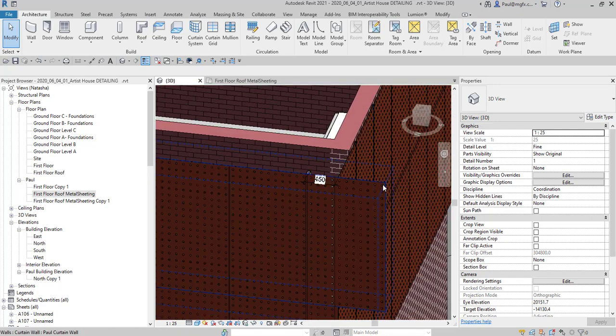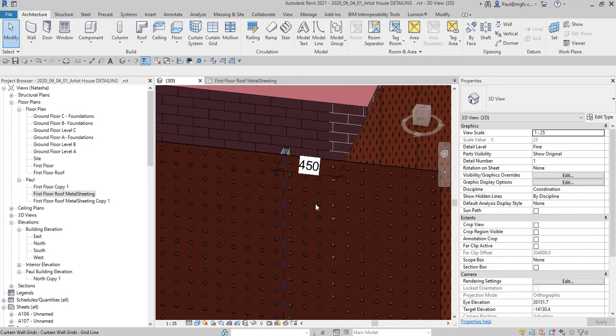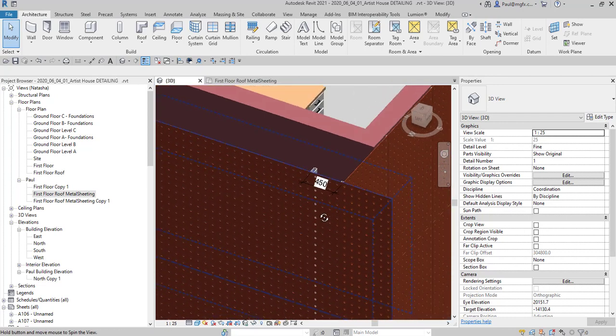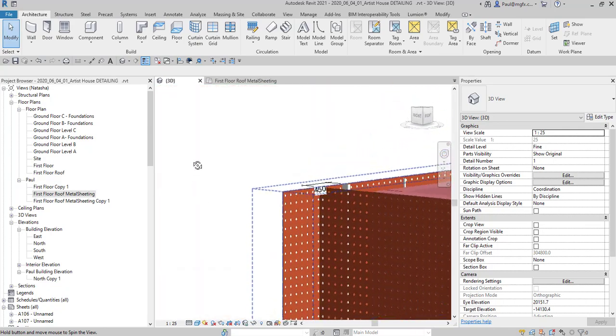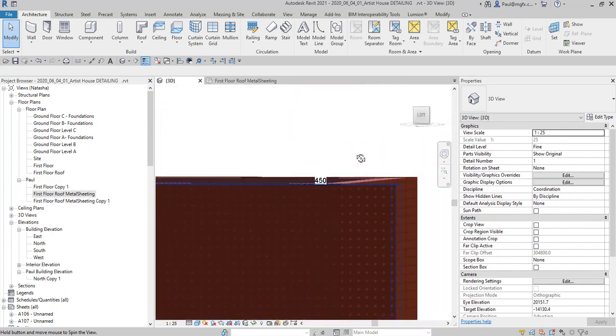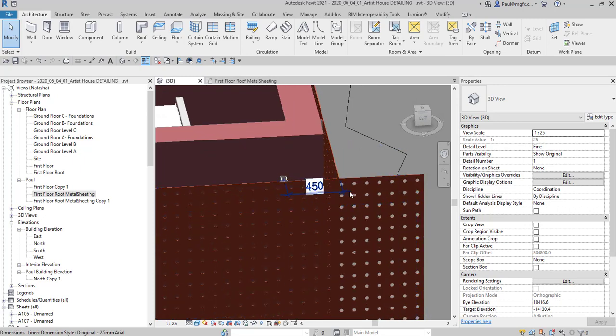If we pull the wall closer, then this panel will deform, and it will fail on generation because the circles will overlap. So we need to handle this exception somehow, and a way in which we can do this is to redefine a panel.